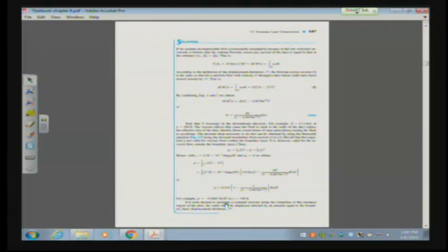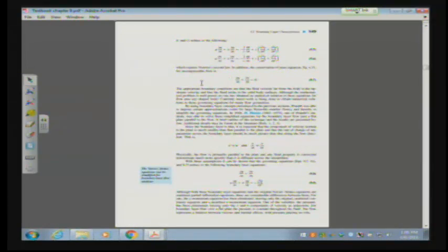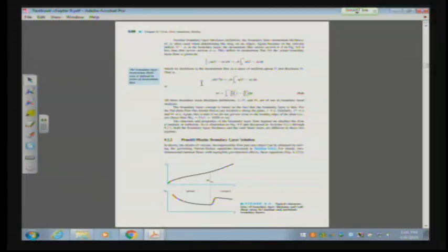So the solution here relies on some of the ideas we've had in the past, but we also equate it to the flow equation for delta that we just talked about. So when you're doing your homework, section 9.3 or example 9.3 is also a good place to start. Now, if we continue, let's come back here, the boundary conditions, 9.2.2 talks about the Prandtl-Blasius boundary layer